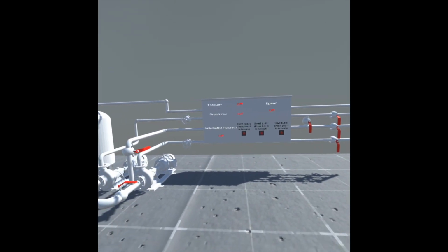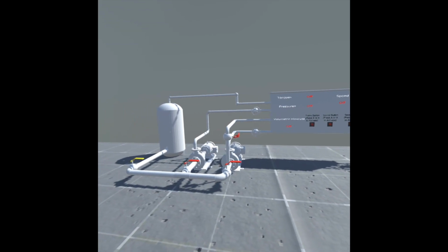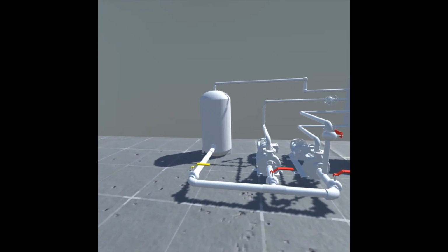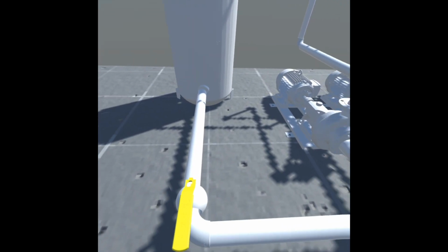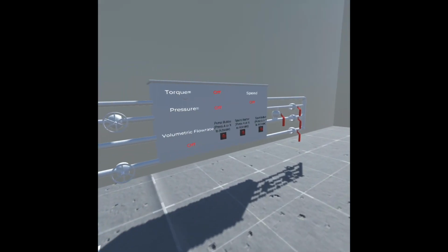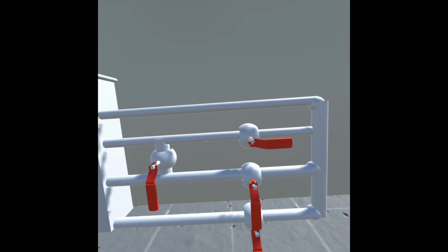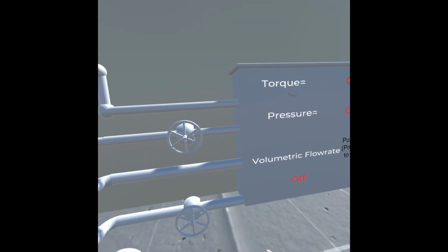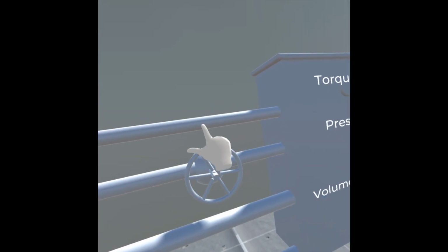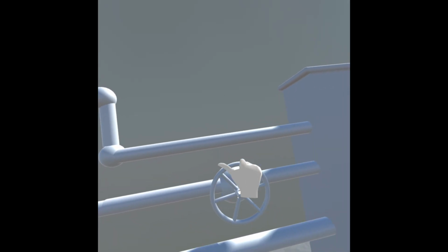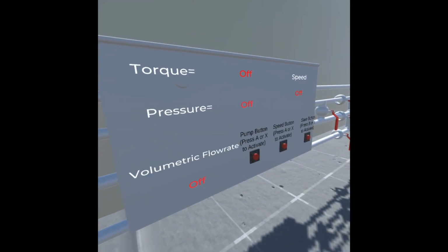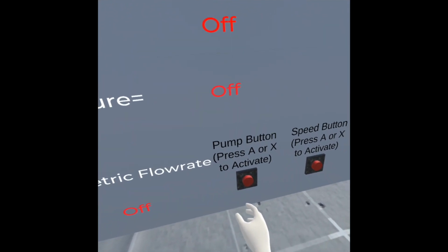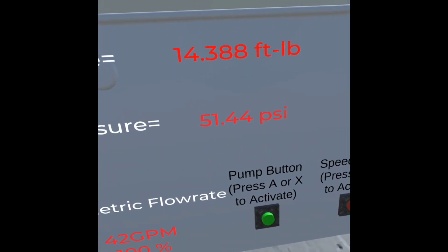Okay, now let's start. First things first, we need to make sure that all the ball valves are open and closed properly so that the pump is in the correct pipe loop. The control valve fully open. Okay, then we can turn on the pump. You can hear the sound of the pump running in the background.